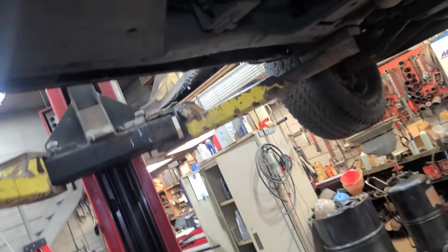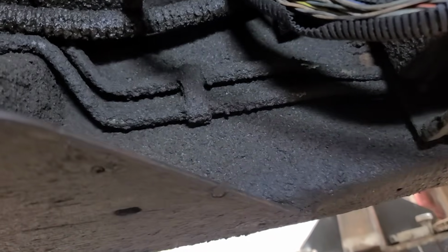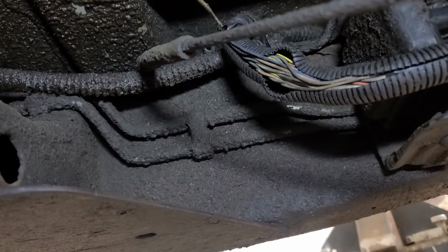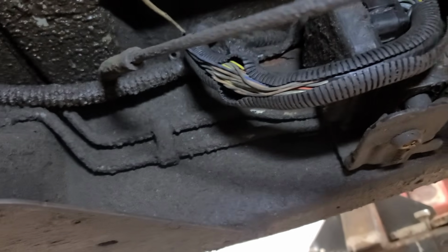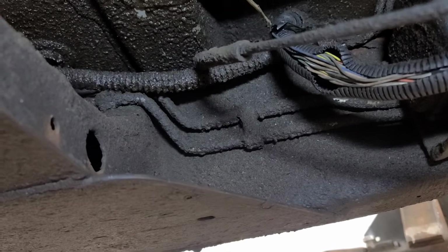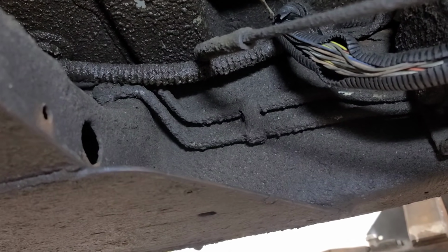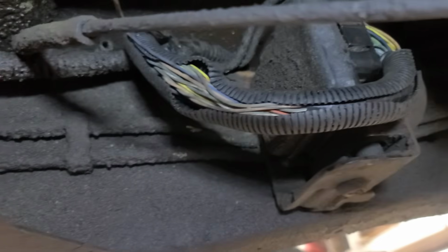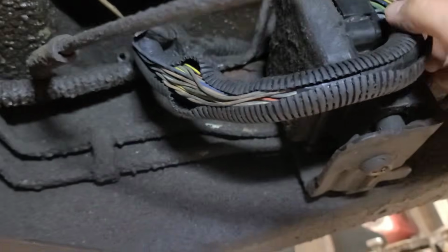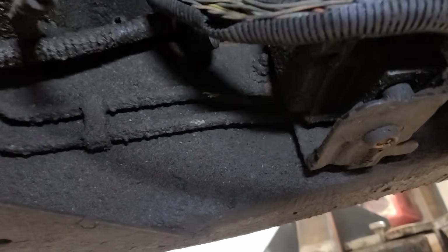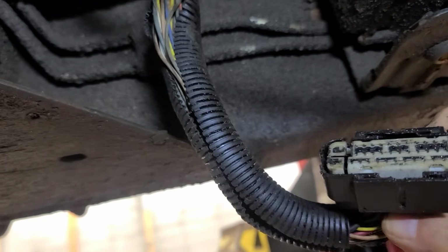Well, we're going to go to the ABS module and disconnect it and see if the resistance changes. I suspect it'll still say 120 because it goes from the IP junction box down here, through this to the module. Now I'm thinking that it's still got communication, otherwise it wouldn't run between the BCM and the PCM. The lock is missing off of this connector. Wow.